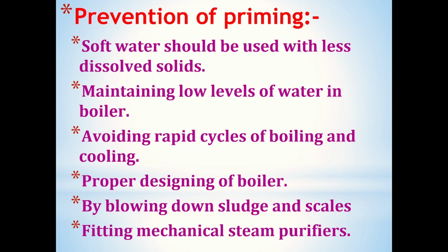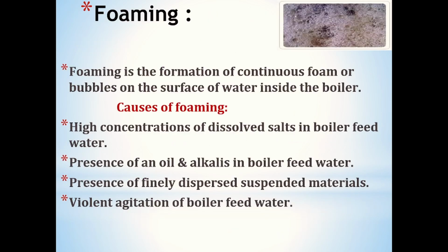Proper design of the boiler, blow down operation by blowing down the sludges and scales frequently, and fitting the mechanical steam purifier avoid the priming. So these are some remedies to avoid the priming in the boiler. Now we are going to discuss the foaming.